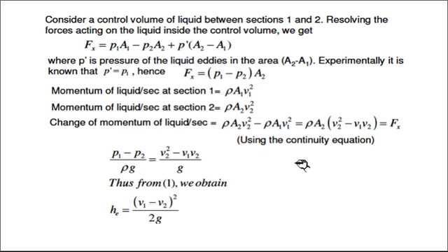The net force is the summation of Fx, and the rate of change of momentum is rho A2 V2 square minus rho A1 V1 square.